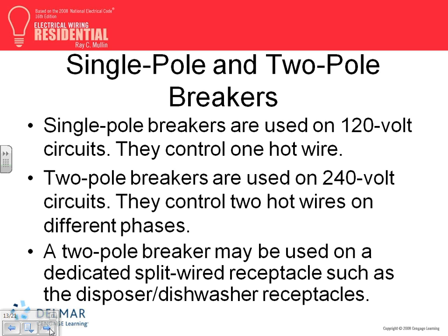So that's the whole idea, guys, of a circuit breaker: to protect you from overcurrent conditions, overload, short circuit, or ground fault. A couple of things about single pole circuit breakers. If you have a single pole circuit breaker, you have to use it at 120 since we're residential. A two pole circuit breaker is going to be rated for 240.